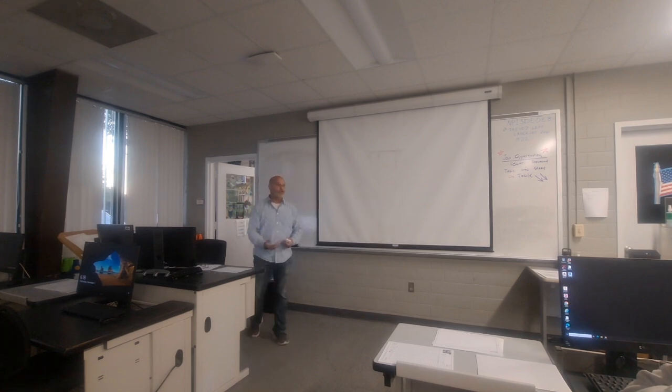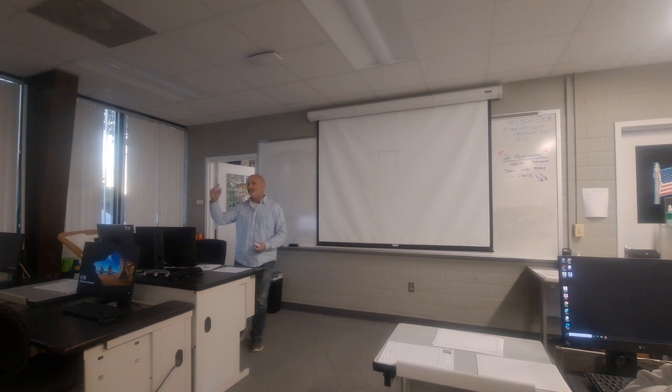You need to be able to get up and ask questions and not just guess and make it look right and fake it. I have seen a couple of people, and I think I've rung it up in about three drawings this semester, of don't override your dimensions. In other words, when you pick that point and put that dimension up there, AutoCAD says 3'6 1/4, and you're like, oh crap, it's supposed to be 3'3". Let me just double click on that dimension and change the text. That doesn't work. It was obvious to me. I see it. I've got ways that I can tell by looking at a printed drawing lots of times. It just jumps out at me.